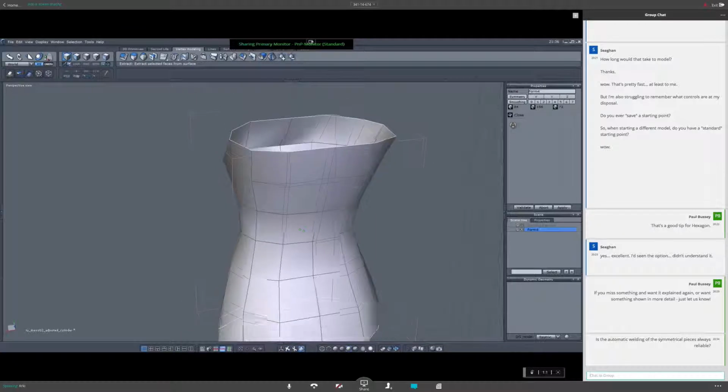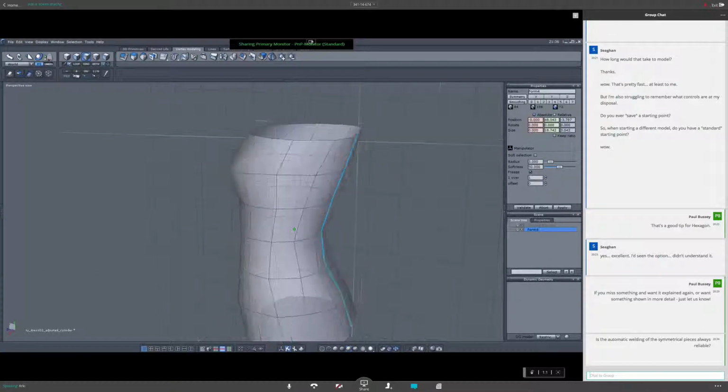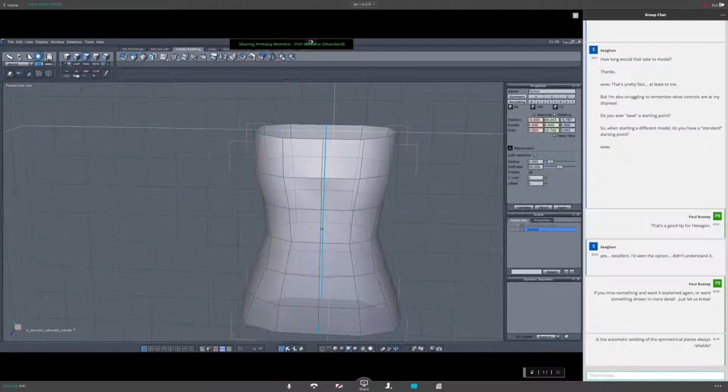Okay. So one way to ensure that your symmetric garment will be mirrored nicely and the weld will be clean is to select this middle axis, I like to call it, this middle edge that should be completely centered in the back and front. And you can see up here, the position is slightly off. It has a negative value for some reason. So select this, delete the value, and just type in a 0.